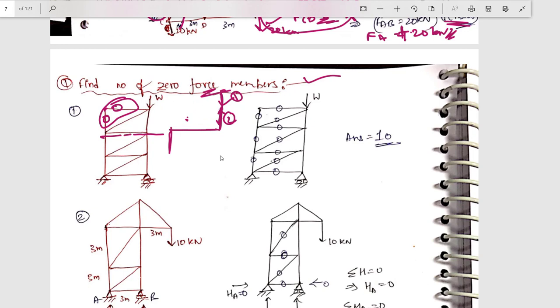Fine. So again, it is very similar to this thing. Now the load is acting here. Again these 2 members are 0, 0. Again you can use that 2 members are collinear. So again this force is 0. I hope you understood, right? And this will continue. Let me show on this diagram itself.